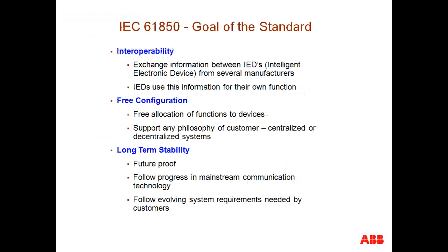Based on those three pictures, let's now take a look and understand what the goals of IEC 61850 as a standard are. The first one is interoperability, which is the exchange of information between IEDs from several manufacturers. Although protocols such as Modbus and DNP offer the capability to exchange information, there are some intricacies that are not defined, where integration comes into play, and we'll see that in a few slides into the presentation.